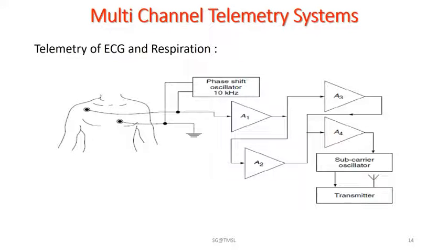Similarly, pulse position modulation, which is called PPM, easily gets into synchronization difficulties caused by noise, and it results in a loss of the information transmitted. On the other hand, the advantages of pulse duration modulation include lower sensitivity to temperature and battery voltage changes, and its adaptability to miniaturization due to availability of suitable integrated circuits.